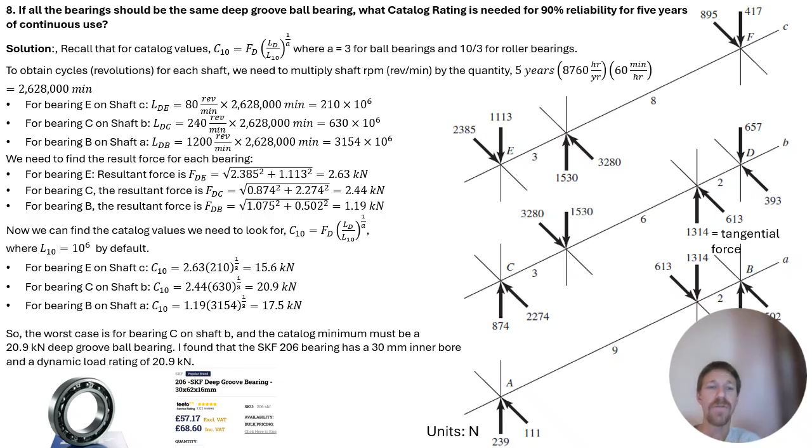No, we don't have an application factor in here. We're just using the base approach. We're not modifying the reliability based on Weibull distribution for 90% reliability, and we've got an exceptionally long life that we're looking for here. So that's how we're building in more reliability in this case, because we're asking for 5 years of continuous use.